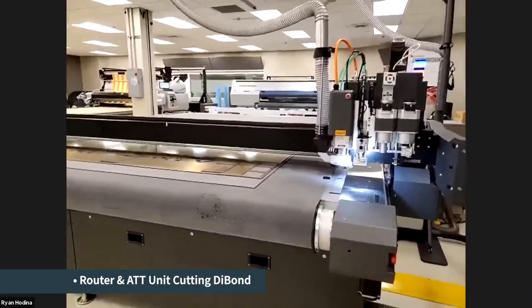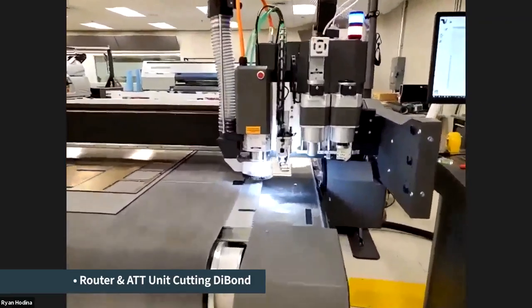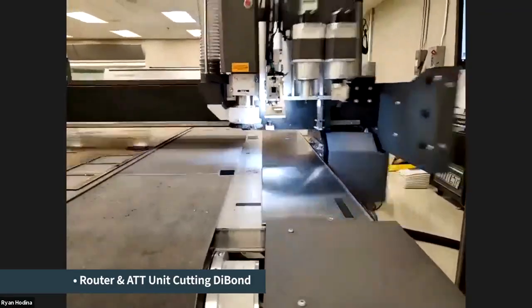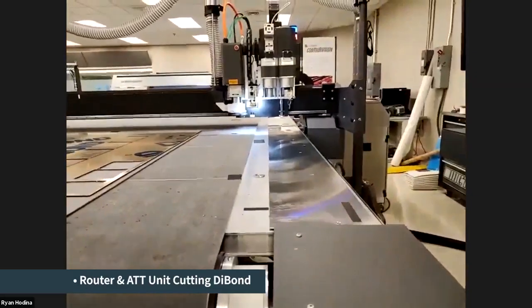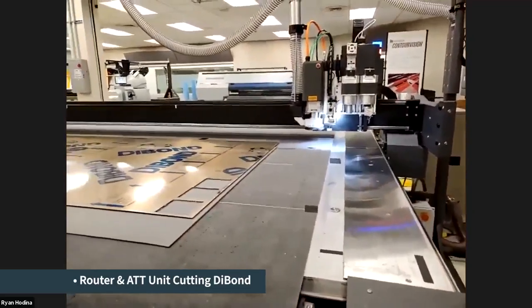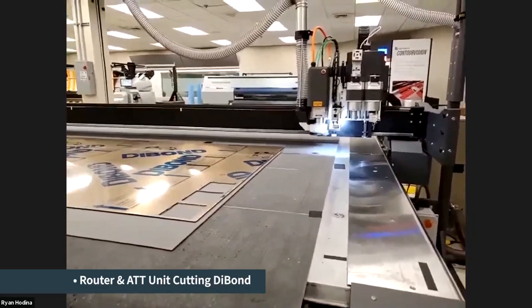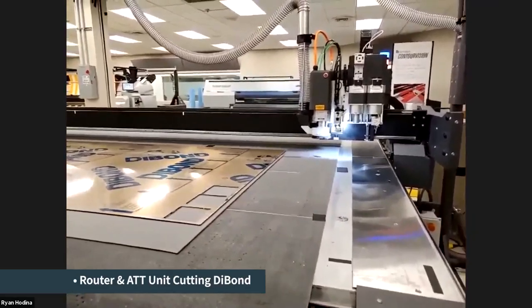Now we're doing the tool touch off. So that's going to initialize the router bit tip on the ATT. So now we know exactly how far the router bit is sticking out. And the motion of the gantry, that's what I'm talking about, how quickly the machine accelerates back and forth. And because of the helical racks that we talked about earlier, that enables us to control the system very, very well.